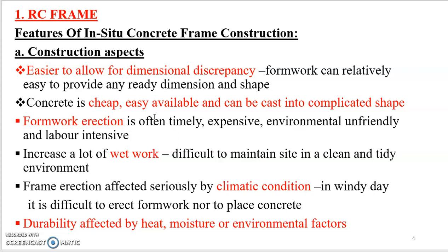Next, what are the disadvantages of this concrete frame construction? First one, the formwork erection is often time-consuming and expensive. Sometimes it is not environmentally friendly also, and it is labor intensive. The next disadvantage is that it adds a lot of wet work, so it is difficult to maintain the site in a clean and tidy environment.